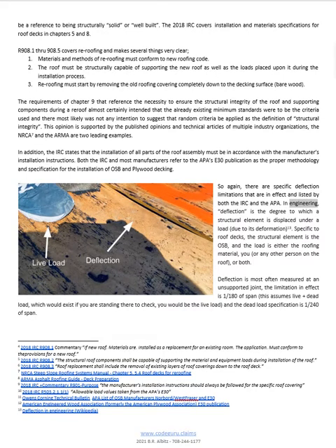In engineering, deflection is the degree to which a structural element is displaced under a load due to its deformation. Specific to roof decks, the structural element is the OSB, and the load is either the roofing material, you, or any other person on the roof, or both. Deflection is most often measured at an unsupported joint. The limitation in effect is 1/180 of span. This assumes live plus dead load, which would exist if you are standing there to check. You would be the live load, and the dead load specification is 1/240 of span.